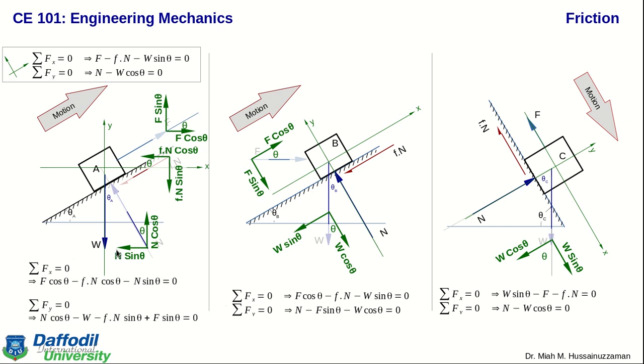So now you can compare these two equations. Here only one among the three forces has theta, cos theta or sin theta, but here all three of the forces have thetas. And for vertical directions, these are pretty simple, only two terms, but here there are 1, 2, 3, 4 components, and among these four, three have theta. So the solution will be a bit tricky, and the figure is a bit hazy, because it is not simple anymore. Previously the figure was pretty simple, right? Now you have to draw components and write these things on the figure, otherwise you will lose your way.